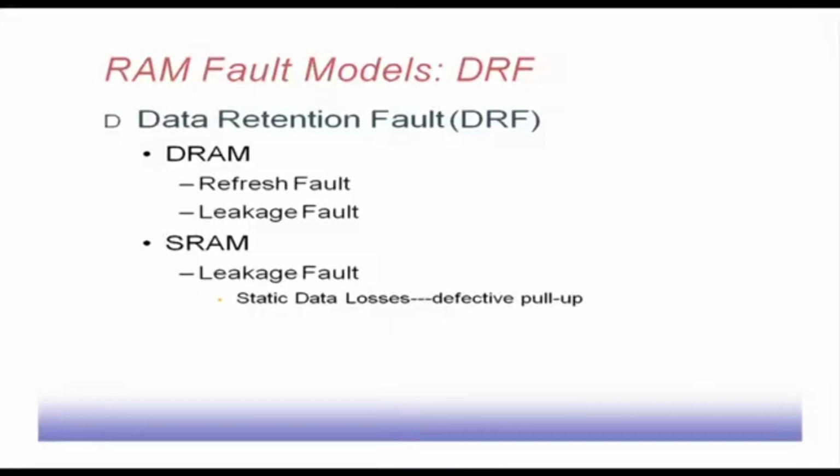Now, due to leakage, these transistors may lose the logic level. That is the static data loss. So, that is the leakage fault for SRAM.